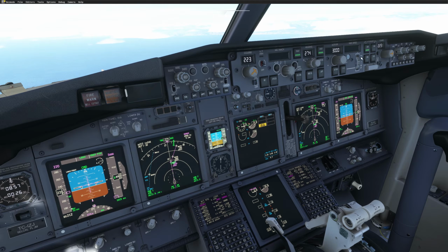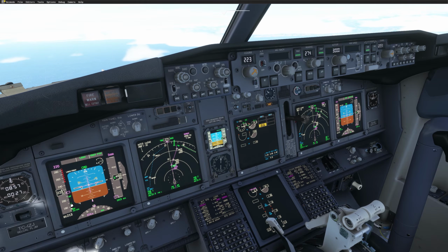Yeah, I wanted to tell you, if you want to descend, do not use level change, because then you will need to change your thrust. The best mode is vertical speed. Now we have to descend, but I want to slow down as well. So what I will do, I will use flaps 1 now. Flaps 1. Speed check, flaps 1. Now the bug will go to 1 automatically. And the aircraft will start to slow down, as you can see.